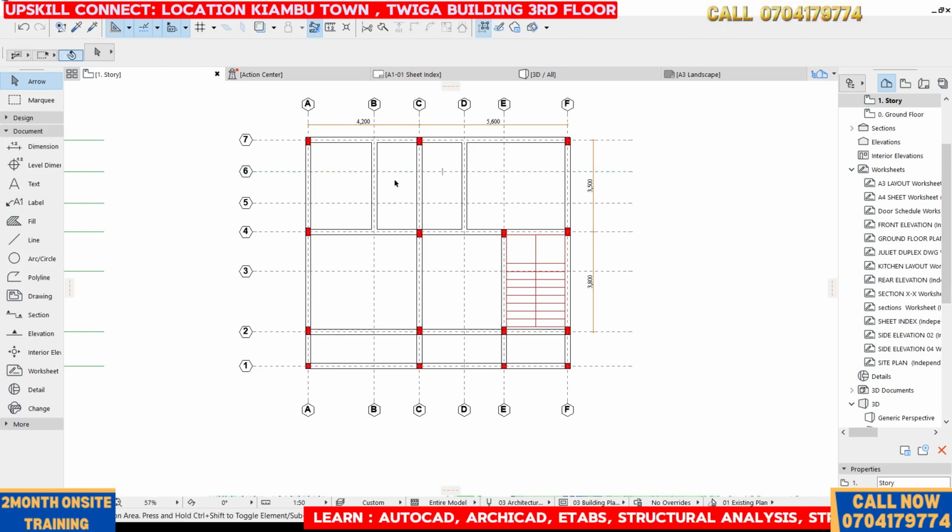Because you want to describe each and every beam, because of things like extra bars, the detailing and all that, it is most important to have each and every beam named individually, all grouped together if they share a certain commonality. For example, if this beam and this one have the same line, the same way that you have the bars and everything, then you can name them to be similar. For example, this beam and this beam probably will have the same configuration and the same type of bar, so those beams can be similar to each other.